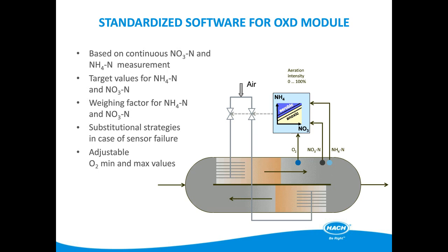You may also have noticed that there is a dissolved oxygen measurement being made by the RTC. This is to override some of the control of the RTC to ensure the DO concentration at a location chosen by the site is always between customer selected values.